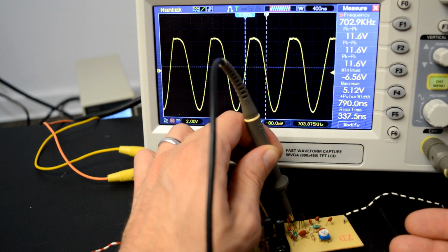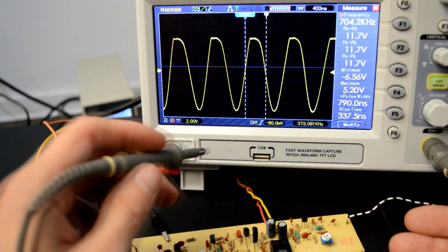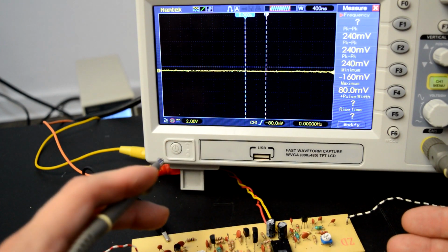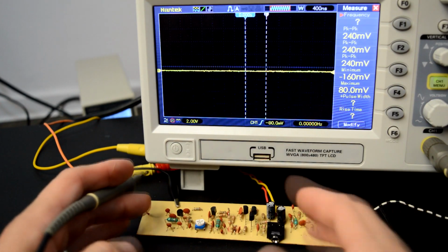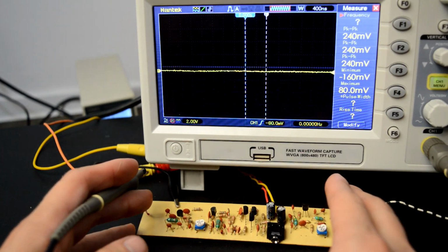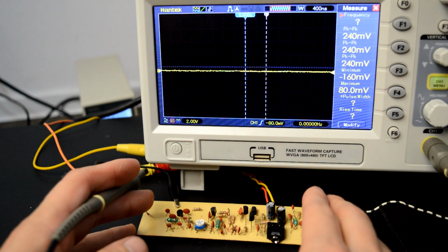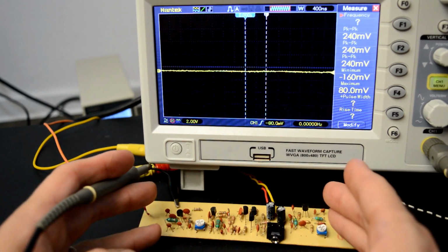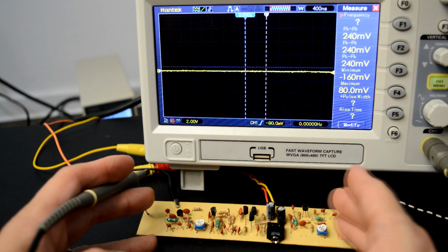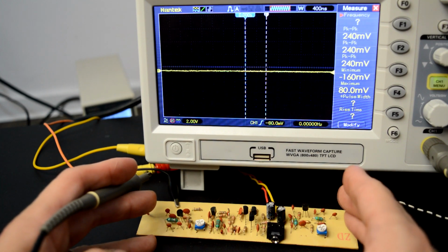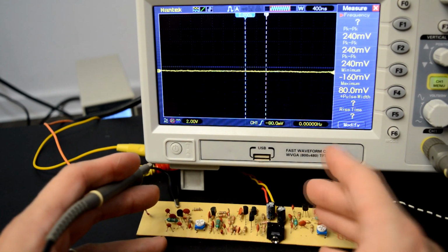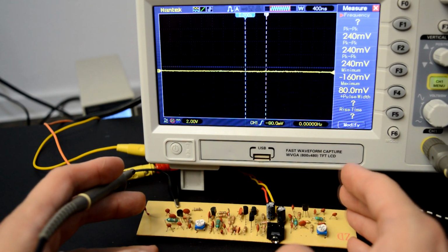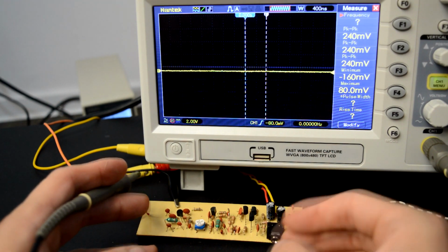The reason for this is that when you're building a Theremin type of circuit, it's important that the volume control side and the pitch control side work at different frequencies. Otherwise, the heterodyne phenomenon could appear between these oscillators, which should be isolated. So it's important that the difference or the sum or whatever mathematical operation between the two frequencies used doesn't end up in the audio spectrum.